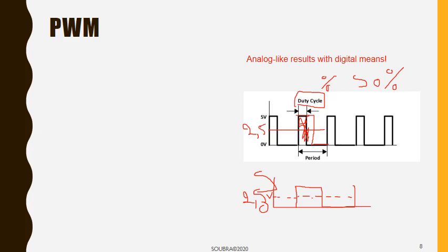If you wanted a higher speed, all you have to do is increase the duty cycle. So let's go for 75%. This means that 3/4 of the time you'll be spending it at high, and 1/4 of the period will be spent at low. Hence, you're going to have 75% of your maximum voltage.